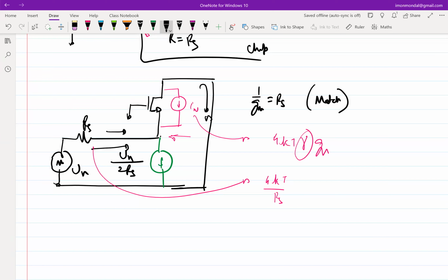But if I have to go for a network which gives me sub 3 dB noise figure, that is, let's say 2 dB noise figure, or 1.5 dB noise figure, or 1 dB noise figure, then clearly these type of circuits are not going to work. Why, fundamentally, is it not going to work? Because in order to match, you are trying to introduce another element which is also noisy, right? So if that is the problem, then the solution cannot be any of these type of topologies.